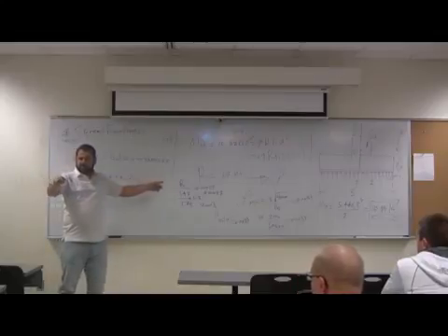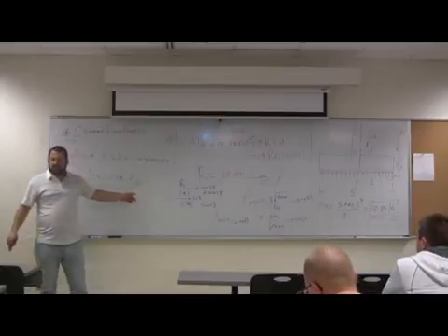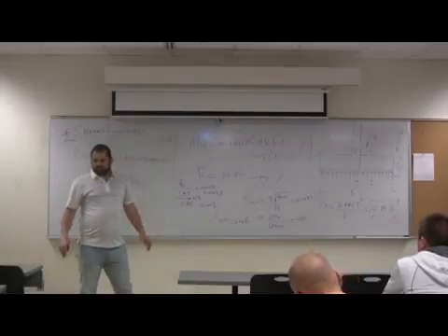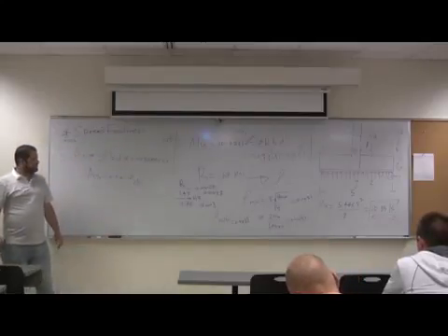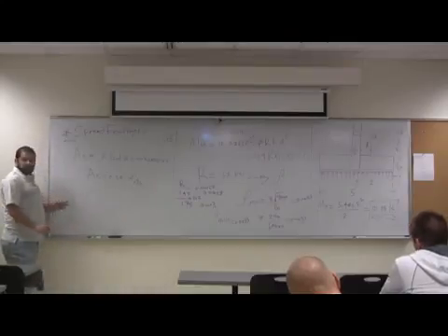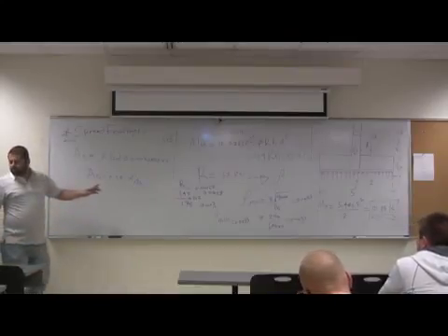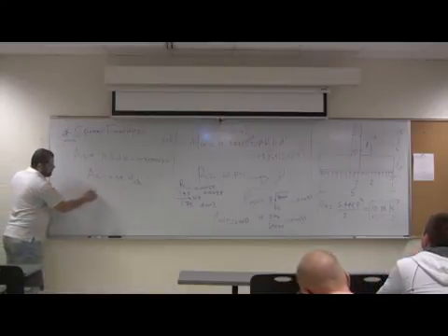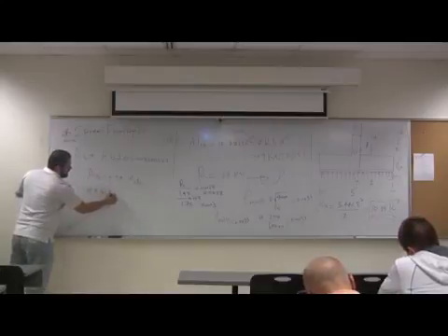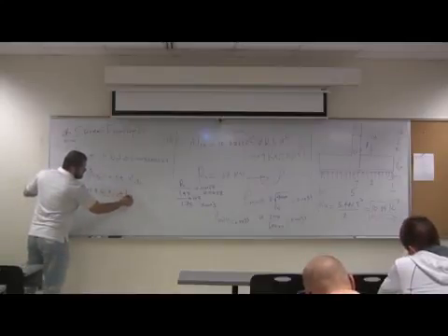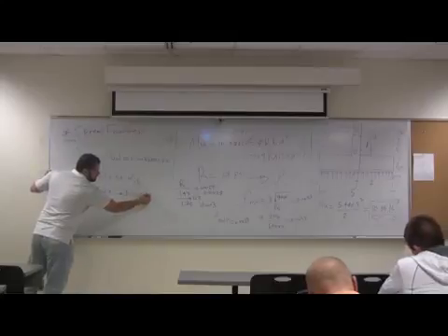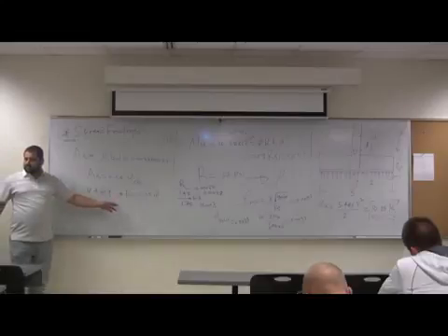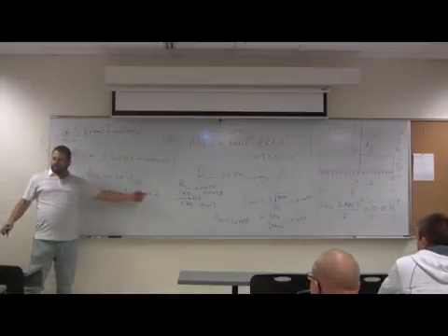You go to the table and tell me what spacing of a given size will give you that. Number 3 at 3.5? That's so close. Number 4 is at 7, so we have the options: number 4 at 7. AS equals how much? 0.34, exactly. Perfect. Take the closest, the first one above it.